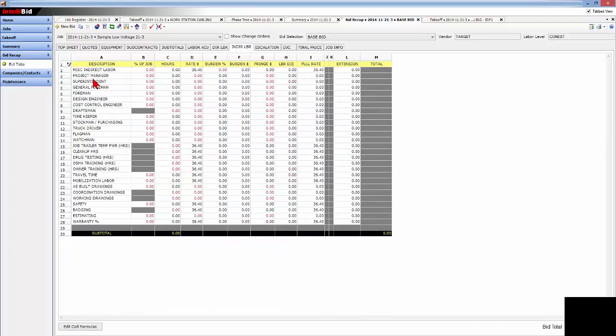Now, indirect labor, project management time. Put some time to manage the project. CAD operator, non-working personnel, mobilization labor, badging in, badging out every day, real strict restrictions on labor forces moving through the building, and even restrictions on the loading dock material handling. So projects that have issues where you could be losing 15% of your manpower, through those conditions you would be able to account for them at the estimate level.